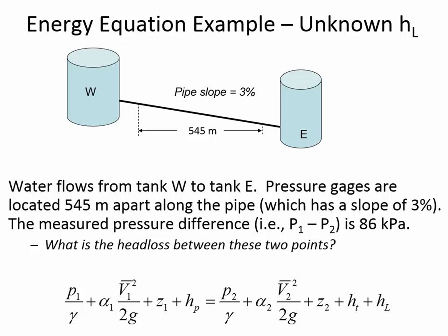You'll remember that in the earlier lecture we did a side-by-side comparison of Bernoulli's equation with the energy equation because they do look similar. There are many of the same terms, but in Bernoulli's equation, its accuracy is only as good as how closely we follow four assumptions. The four assumptions being: an inviscid fluid, meaning that it has no viscosity, which is incompressible, which is for steady flow, and applied along a streamline. So those were the four assumptions that we had to use with Bernoulli's equation.